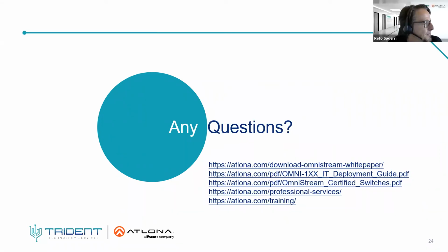We have a few questions. Yeah, I will go with the first one. What is the audio network protocol you're using? So from the encoders, we are sending AES67, which is related to Dante. It's sharing most of the protocols, but it's not one by one. But it's supported by most of the DSPs that also support Dante. And then the amplifier I have shown, the Gain 120, can be equipped with a network audio card which can receive Dante and AES67.